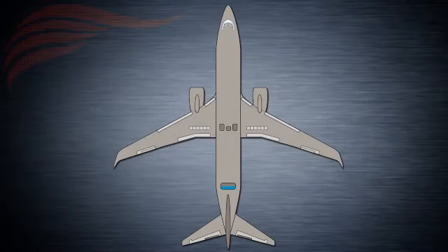Specifically on the 737 NG, bleed air is used to power the following aircraft systems: Engine 1 and 2 start systems, air conditioning and cabin pressurization, Engine 1 and 2 cowl anti-ice systems, wing anti-ice systems, water tank pressurization system, hydraulic system A and B reservoir pressurization system, and a few other minor elements also rely on bleed air, such as air temperature probe aspiration systems or nitrogen gas generation, among others.